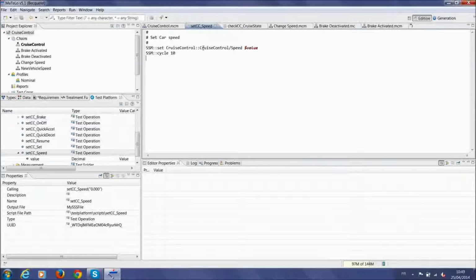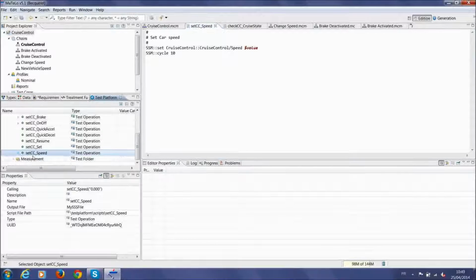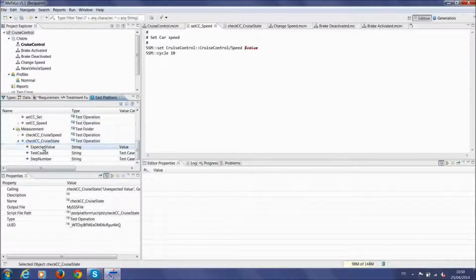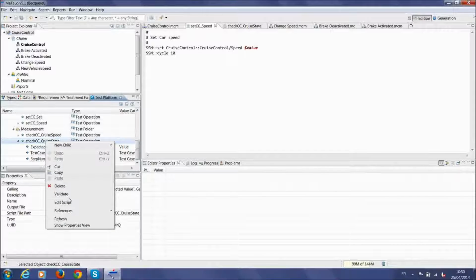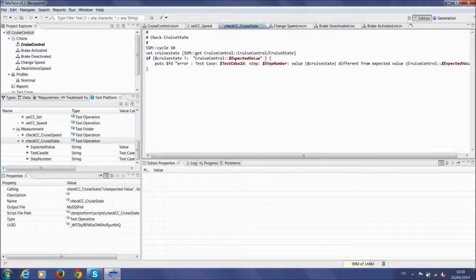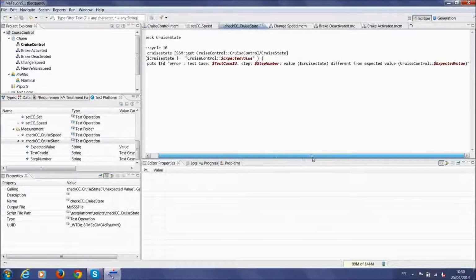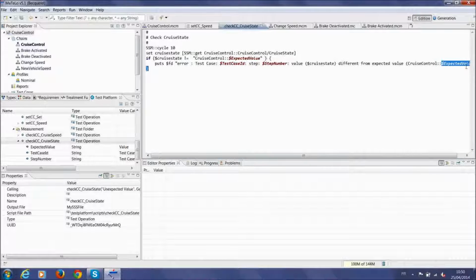To create the test cases from the model, select the generation window with the help of the button on the top left. Select the default strategy or create your own strategy. Select the substates of the model you want to parse or include in the generation. Select the appropriate algorithm to fit your test strategy. Click on the Generate button.